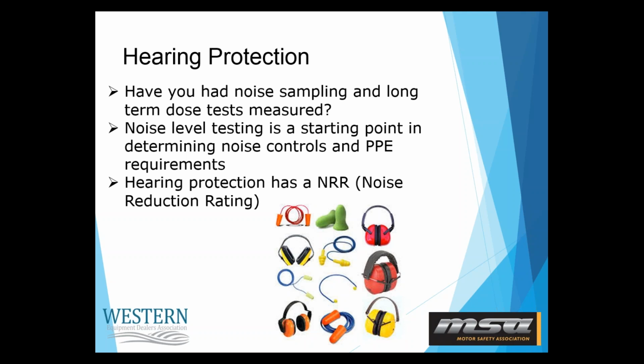And sometimes I find quite interesting, especially in detailing areas of automotive or agricultural, those types of businesses, people who are running pressure washers and shop vacuums, they're exposed to levels of noise from the pressure washer and vacuum for long periods of time. And because these decibels may not seem as loud as what an impact wrench would be, sometimes people have missed out that hearing protection should be worn in those types of environments. So it's good to get those noise levels tested to give you that starting point to help you determine your requirements for PPE.